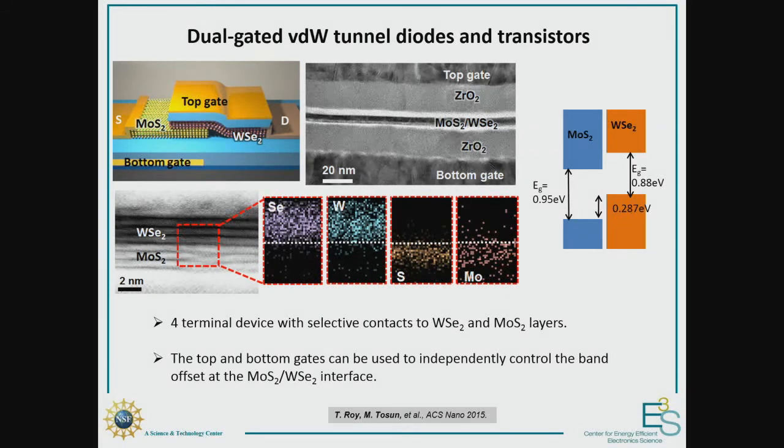There is no doping involved. And that's a unique feature. Ideally, you want to move away from doping because doping does, in principle, induce band edge tails. It reduces the band edge sharpness. That's well known. So this is a high-resolution TEM of the device. You can clearly see the heterobilayer. There's the bottom gate, top gate. It's a symmetric device.